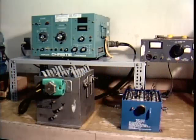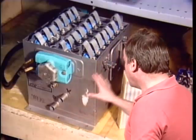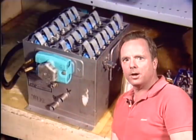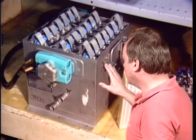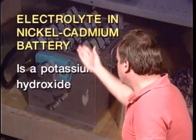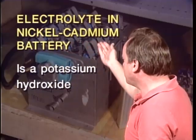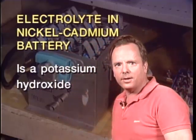Now let's take a look at nickel-cadmium batteries, or NiCad batteries. As you know, NiCad batteries generally are used in turbine aircraft because they have very little internal resistance and they can put out a tremendous amount of electricity in a short period of time. What is the electrolyte used in a nickel-cadmium battery? It's potassium hydroxide, and you need to remember that on the test.